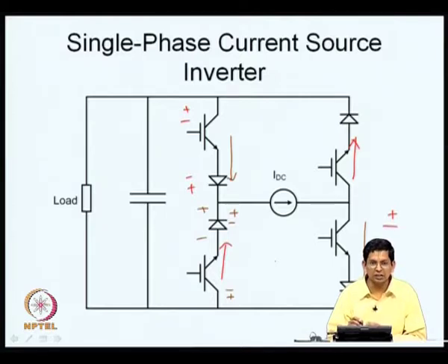As I mentioned earlier, a thyristor is a natural option to do this, but we can also use a transistor in series with a diode, the so-called anti-series connection. Why anti-series? As I mentioned before, you may have something which can block in one potential and another element which blocks in the opposite potential. So, let us say we take this transistor. This transistor is capable of blocking with this potential, whereas the diode is capable of blocking with an opposite polarity, while both of them conduct in the same direction. So, you call it an anti-series connection.